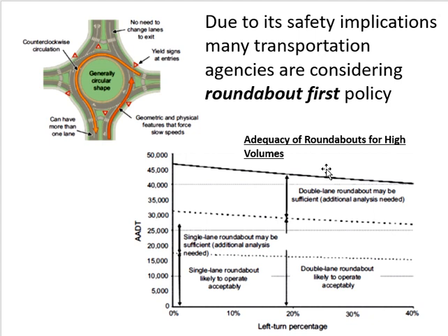Now, with roundabouts, you can have a 2-lane roundabout or a single lane roundabout. So there's a graph. Obviously, there are other methods as well. You can do detailed calculations. There's a whole procedure to calculate the capacity and find out the number of lanes according to that. But this is a shortcut according to average annual daily traffic and percentage of left turning.